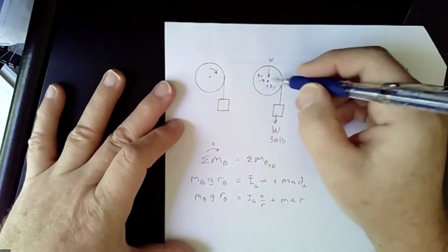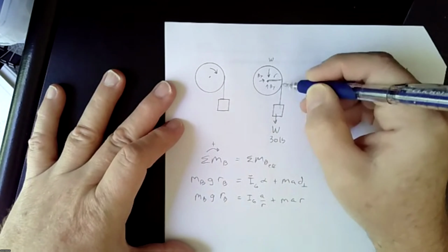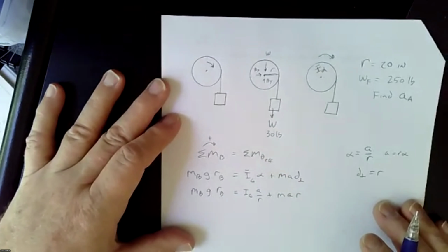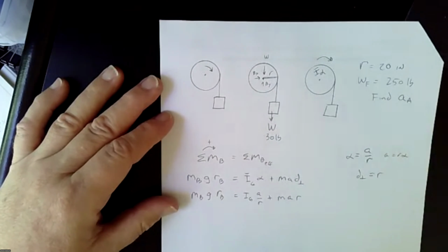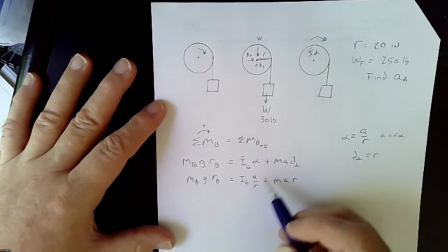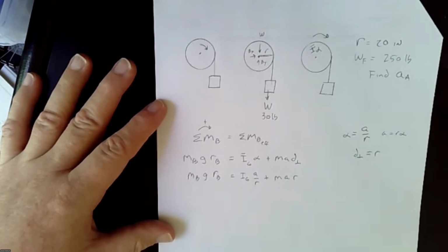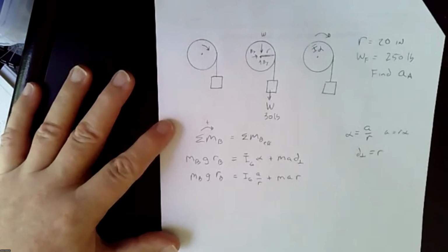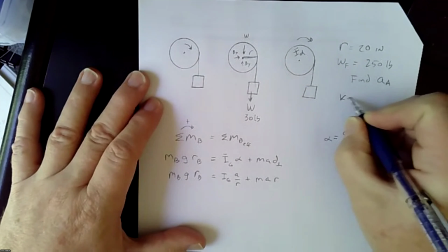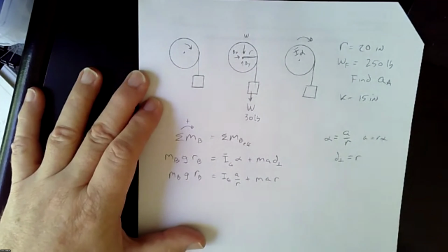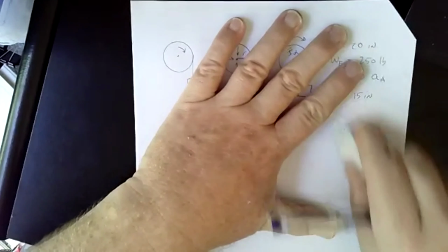If you think about it, here's the acceleration, there's the R distance, and there is the acceleration down, causing it to rotate. Okay. You don't put the M A D on this diagram. In fact, this diagram only has the I alpha on it. Now, in this case, we actually have angular acceleration, so that doesn't drop out, unlike the previous two problems that we did. Now, another thing to note is we are given that the radius of gyration, K, equaled 15 inches. Okay. So that's nice because, and I'll erase this and I need more room.